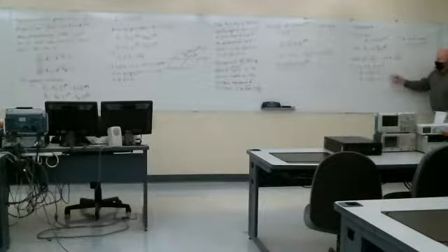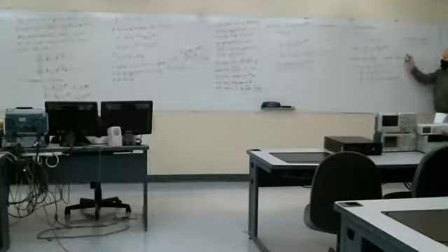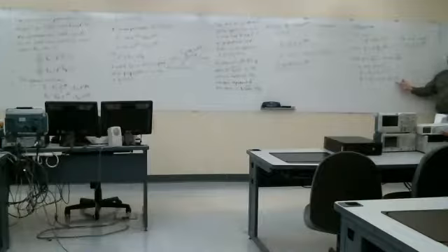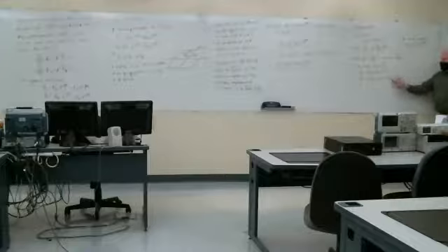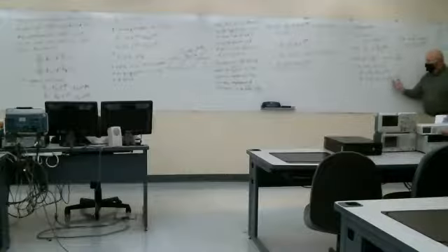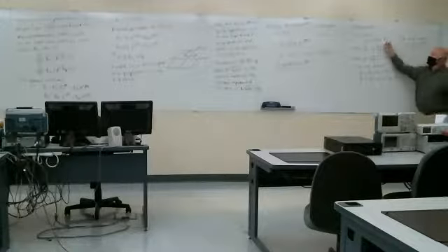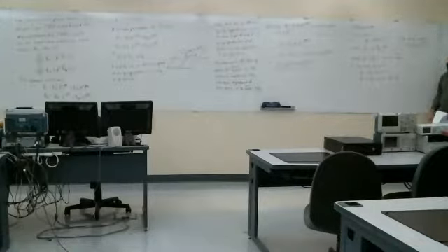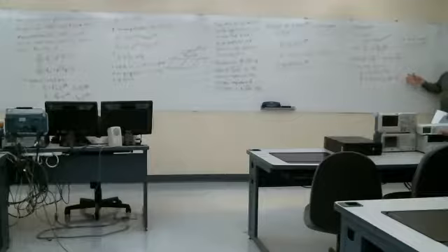Again, E is given by this, E0 is this complex constant, so the phase angle of our complex constant appears in our cosine. So this is just like working with phasors in circuits, right? Our phase angle here is e to the minus j beta z plus j psi, and then E0 e to the j psi forms my E0 constant. So those both come right into my phase angle in my expression. So this is my vector expression for my electric field.